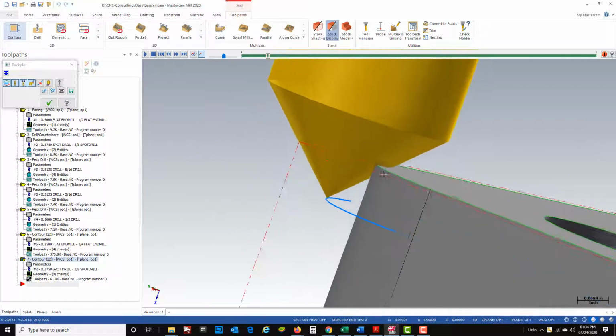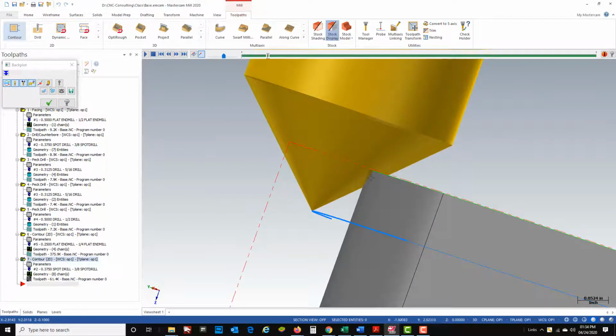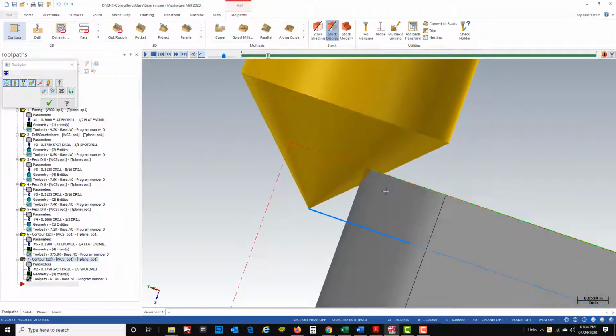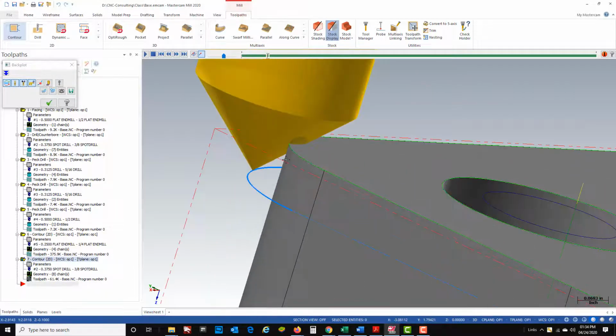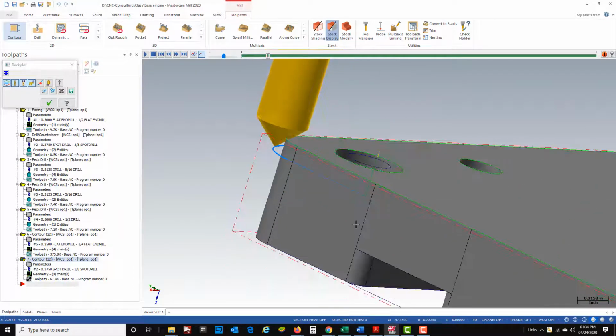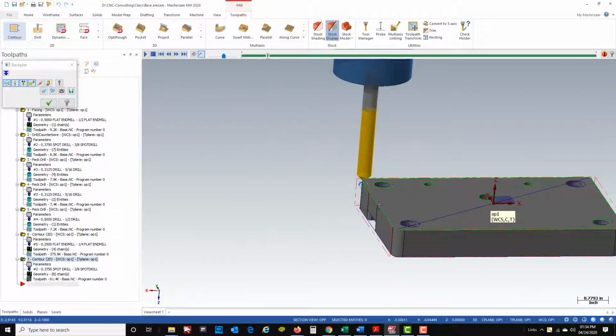Now you can see that that toolpath is cutting a nice light chamfer into that part. And that's what we were looking to do. And to adjust your chamfer, you would give it either a larger negative stock allowance or give it a deeper Z in your linking parameters.